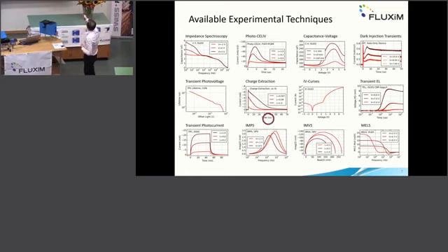And last but not least, a technique that we have invented, called MELS. It's like impedance spectroscopy, but you look at the electroluminescence signal that comes out from an OLED, and then you calculate again this quantity. From that, you can also learn some things about charge carrier mobility, for example.